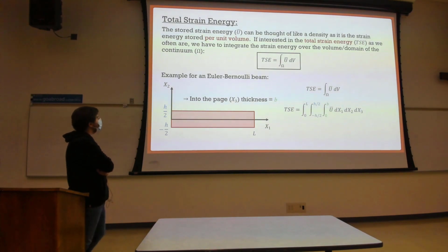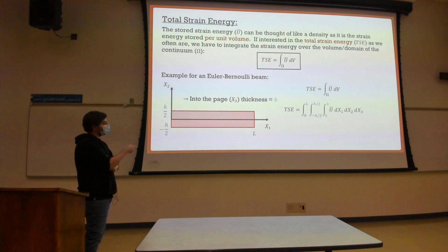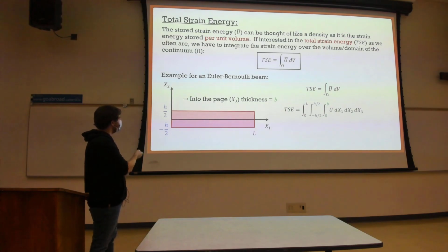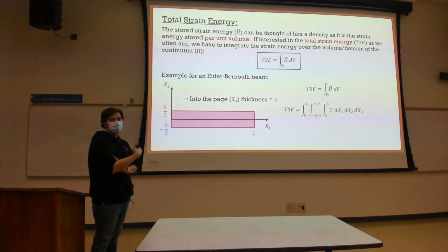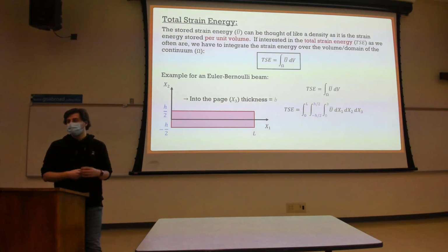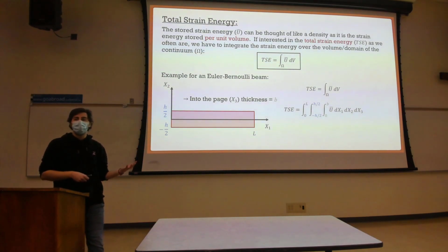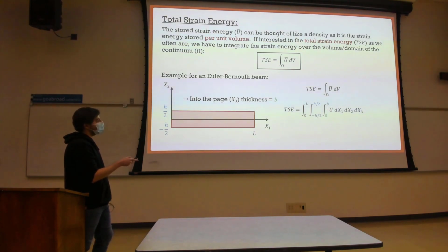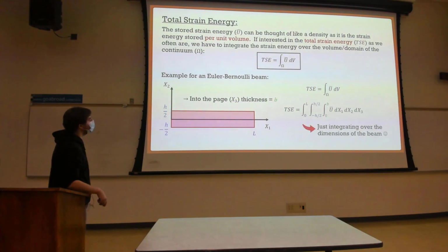But what we're going to do is discuss certain cases, like Euler-Bernoulli beams, because it actually simplifies quite a bit. For an Euler-Bernoulli beam, have you ever seen the cross-section vary as a function of x? Euler-Bernoulli beams, beams under flexure. Have I ever given you a varying cross-section? No. Beams under axial load I have, but not Euler-Bernoulli beams. So if the area isn't a function of x1, x2, or x3, can I just take it out? Yes. So that's what we're going to do, we're going to look at some of those scenarios.